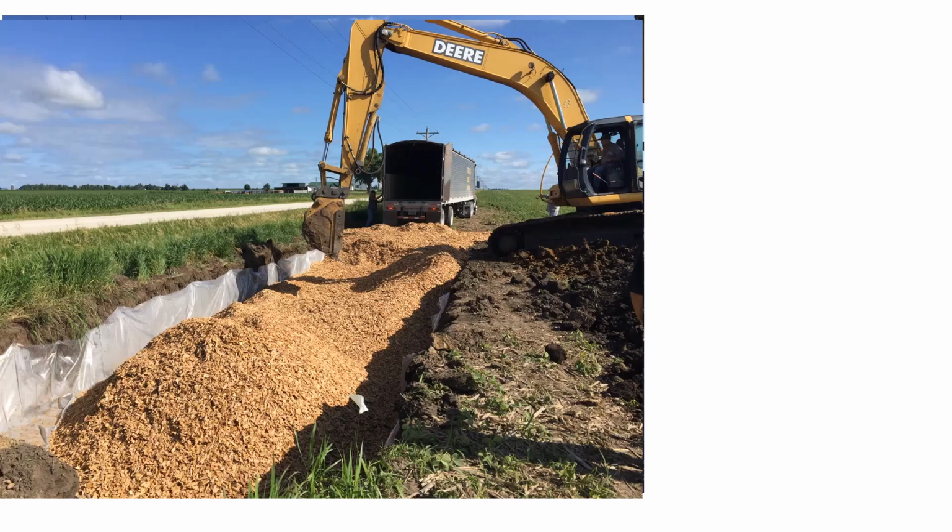Anything more, compaction may become an issue where you might compact those wood chips too much and not get the flow that you want through the wood chips. I always say order about 10% more of the wood chips, just in case you get a little wide on one end from your design specs, or you're a little bit long.